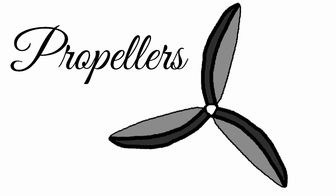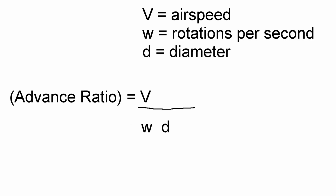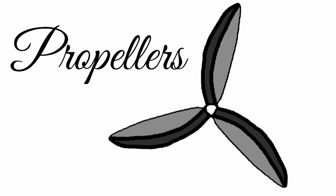Efficiency. The larger the diameter of the propeller, the more efficient it will be. This is because power from the engine is constant and the RPM can drop. Efficiency goes down as airspeed increases. Advance ratio. The efficiency of the propeller will be the same at the same advance ratio. Advance ratio equals airspeed over rotations per second times propeller diameter. Equation 3.1. A propeller blade normally operates at a Reynolds number of 100,000 to 400,000.